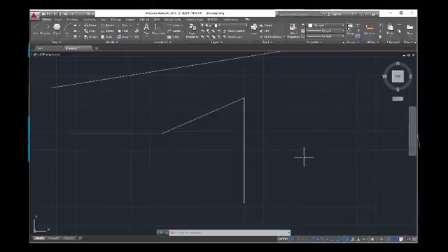Now that you have a good sense for how to draw lines, let's practice deleting them. There are lots of ways to delete objects that you have drawn. The first way is to simply click on the line. So let's select one of the lines that you drew previously. Hover your cursor over the line and you'll see that it highlights in white. That means you're about to select something, and notice it does it at the center of the crosshairs of your cursor. Click on the line and you'll notice that it actually highlights the line in blue. This is how you know you've selected the line.